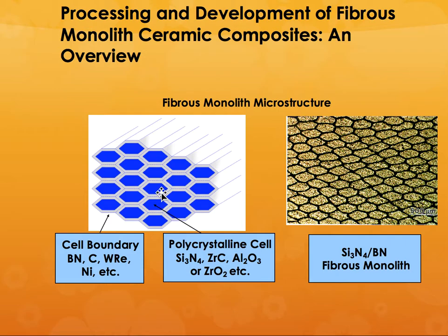You extrude that one time, you have these small fibers, then you bunch them up together and you extrude them again, and you get smaller and smaller and smaller fiber sizes. So you may start with something like 50 to 200 microns, and then you end up with something like 5 to 10 micron sized strong areas and about half a micron of weak area.